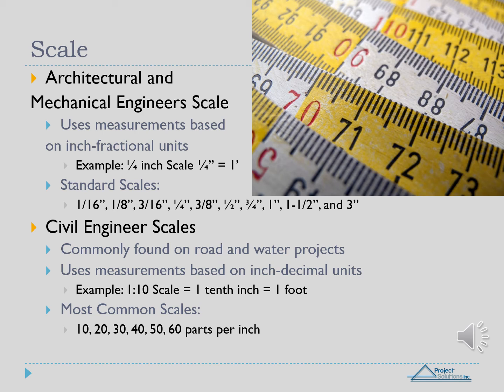As an example, in an architectural or mechanical drawing, a 1/4 inch scale indicates that every 1/4 inch is the equivalent of 1 foot. A good set of 6-sided architectural and engineer scale rules will have most of the standard scales on them for manual takeoff. Also, make sure your plans, if printed, are printed in the correct size or your scale will not be accurate.